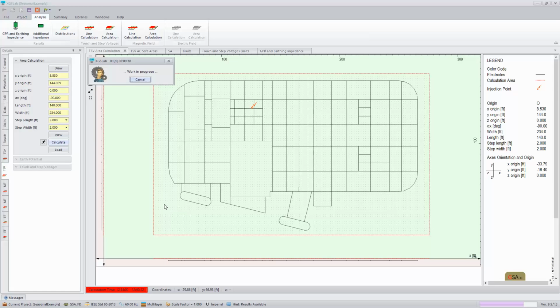It's a similar concept for the step. However, we're not looking to compare to the grounding system's voltage. Now we're just looking to compare between dots, assuming the person's stride length is 3 feet. We'd be looking in a sphere of 3 feet from one dot to the next.